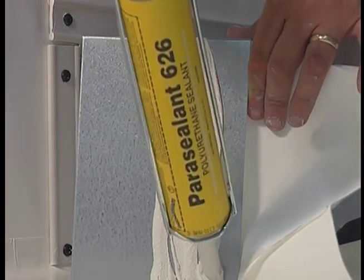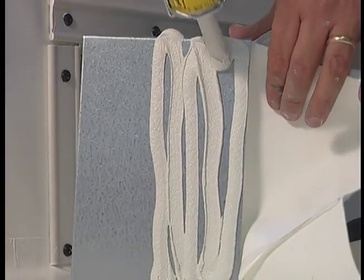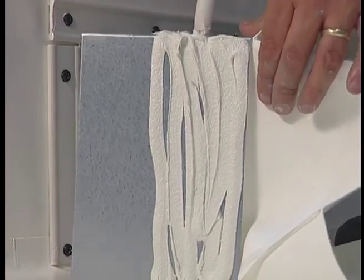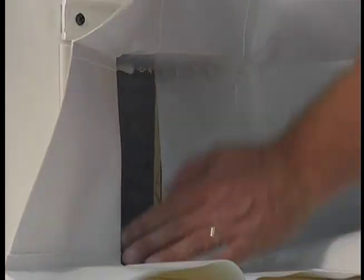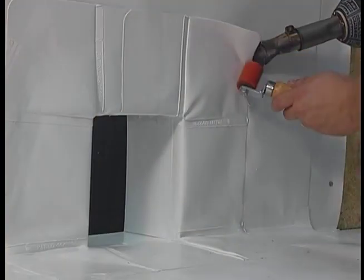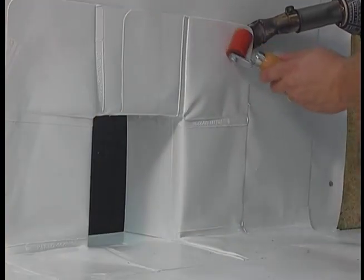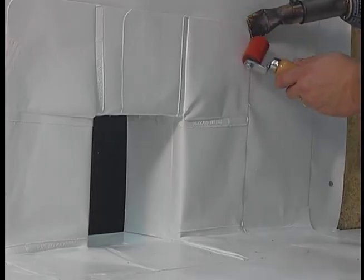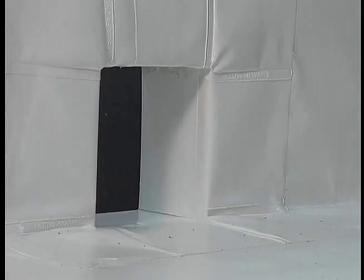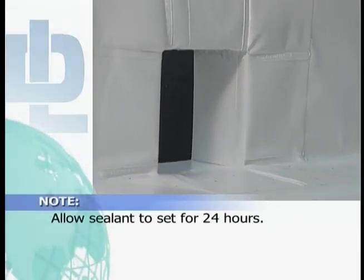To adhere the scupper to the inside of the walls, apply Duro-Last sealant to the outside of the scupper surface. Slip the scupper liner into the hole and position it properly. Heat weld the skirt to the parapet and deck membranes and to the wall flashing covering the termination bar. Heat and bend a termination bar to wedge the scupper in place until the sealant cures.